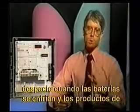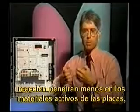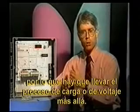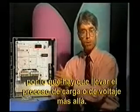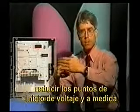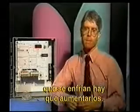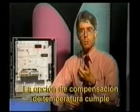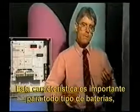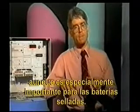As batteries get cold, the chemical reactions are going slower, and the reaction products are penetrating less into the active materials on the plate. We should take the charging process, at least the charging voltage, further. So, as batteries get hot, we want our voltage settings to be reduced, and as batteries get cold, we want our voltage settings to be set higher. The temperature compensation option will automatically do this for you. This feature is important for all types of batteries. It's especially important, though, for sealed types of batteries.